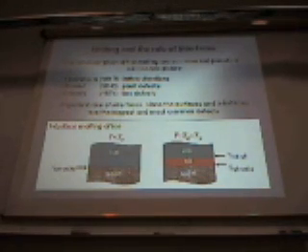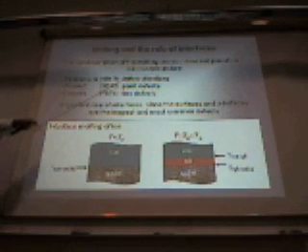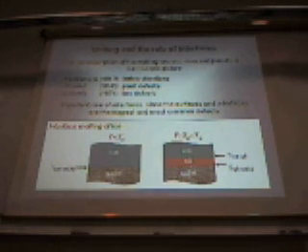There have been various mechanisms proposed, like the original Lindemann criterion. That means when the lattice vibrations get too big, usually somewhere in the range of 10 to 14% of the nearest neighbor distance, then the bonds break and the lattice is destroyed and it melts. Franklin suggested that point defects play a big role. Cottrell puts the emphasis on line defects, and there have been lots of other